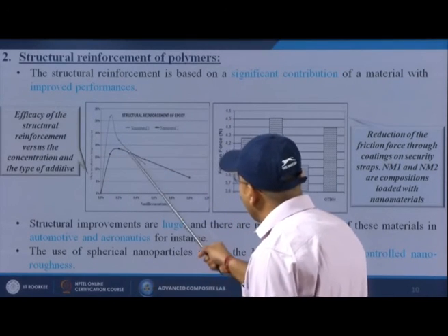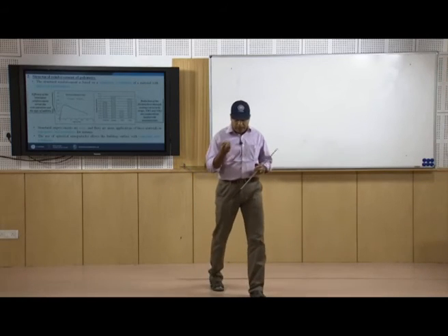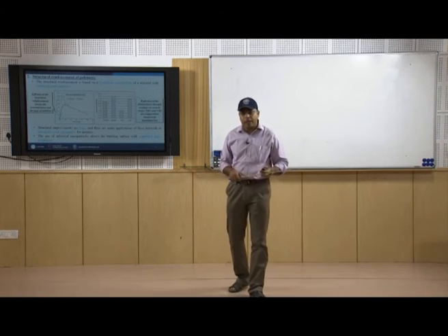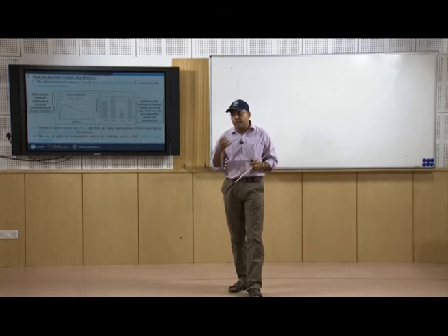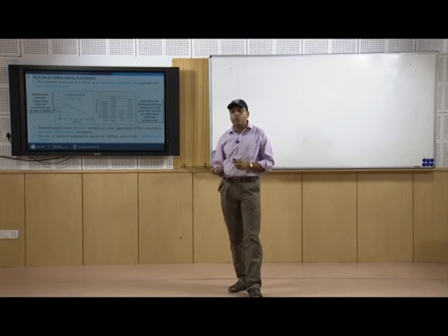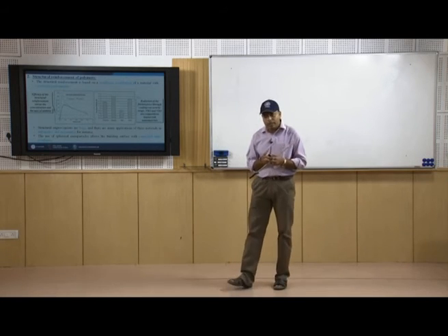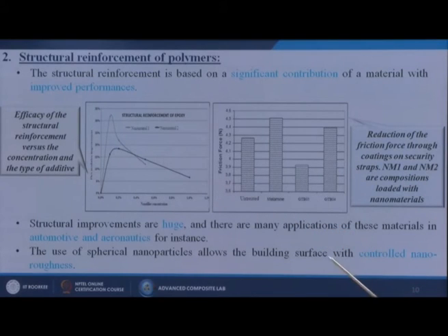So, when we go for a small particle size, that small particle size and small concentration is equally distributed into the matrix composites, which gives you better properties. But when you increase the concentration of those nanoparticles, the properties automatically go down. That means the nanoparticles are making agglomerations inside the matrix, or inside the composites, which is reducing the material properties drastically.